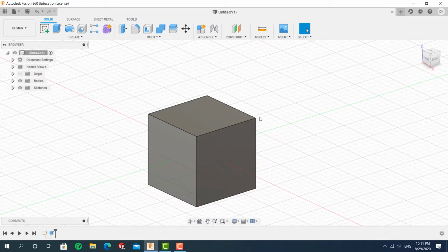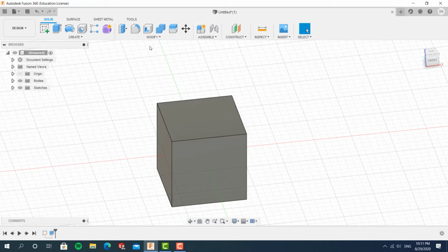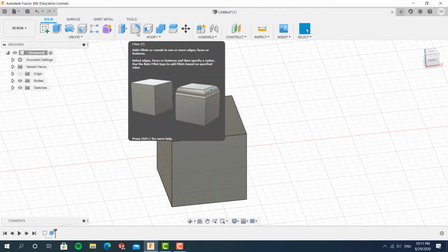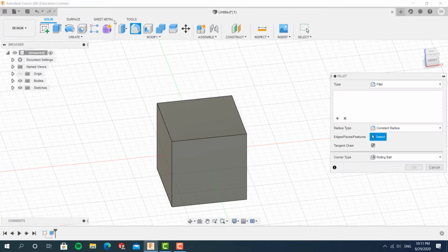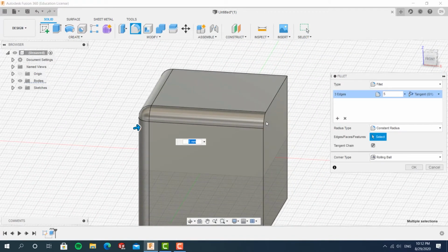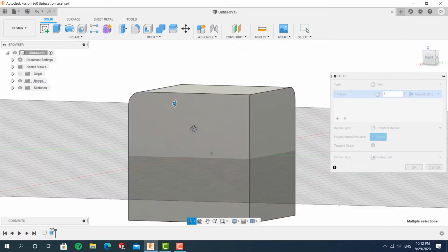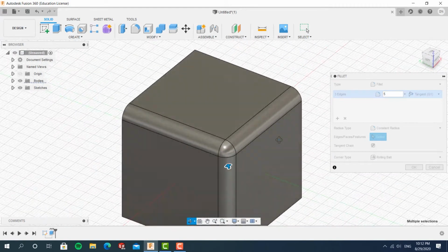The thing about a cube is that if you have the whole thing right here, it looks a bit silly. You never see a die that is a perfect cube because that just looks silly. So one of the things that you can do is use this function over here. Basically, this function is going to smooth all of the edges. Let's take, for example, let's smooth down these three edges. If I add a 5, it's going to smooth down so that the radius of this cut right here is going to be 5.